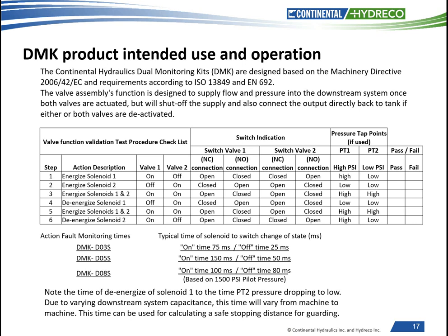Here you'll see that we do list the action fault monitoring times. When I energize a valve, what duration of time should the controller be looking for a change in state, whether it's turned on or whether it's turned off? These response times are listed here.